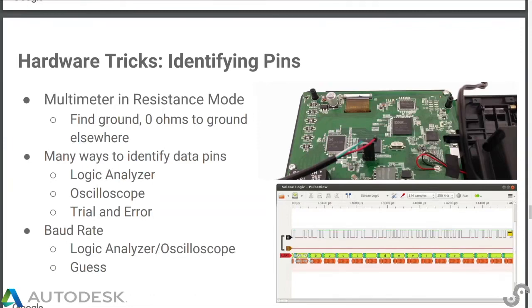So on most devices, I've never had one have a problem with this. Most of the time, I'm lazy. I try the RX and TX one way. If it doesn't work, I swap the RX and TX, and then it usually works. That's the lazy way to find it. There's usually not a problem with that. They're not sending enough current to cause damage if you have them backwards.